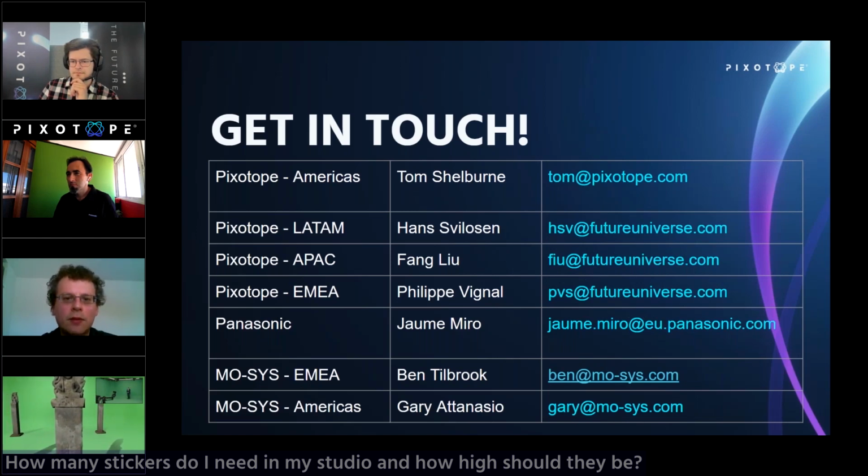I think we generally tend to have them spaced on average about one tenth of the height from the floor to the ceiling. In our studio, which is around 3.5 meters, we have them around 40 centimeters or so spaced out. And for the floor-facing ones, we tend to have something similar, 20 to 30 centimeters apart is good. But the system is very flexible, very permissive. So if it looks reasonable, it can track off it.